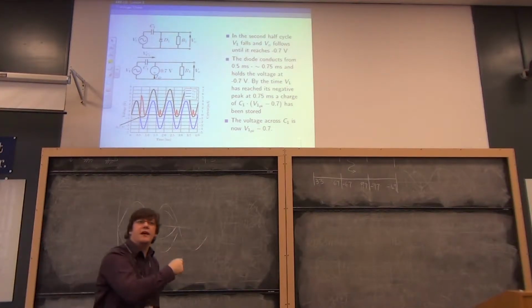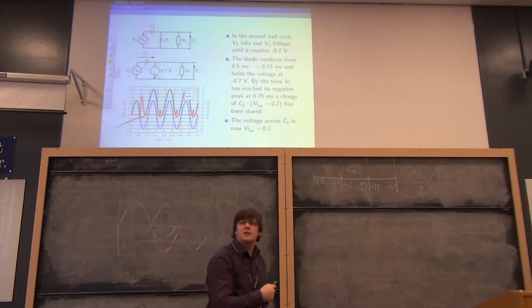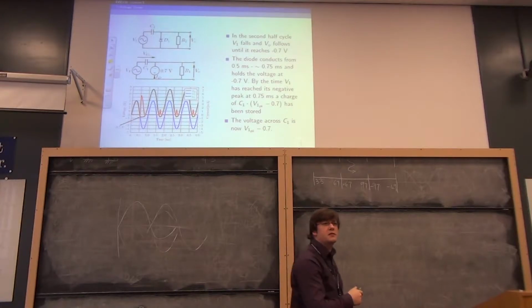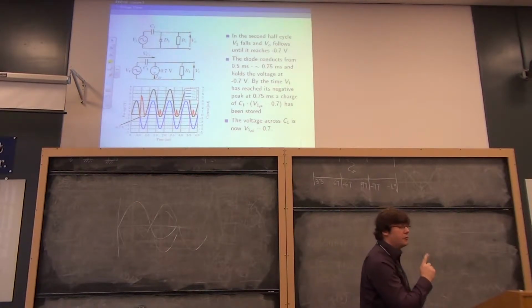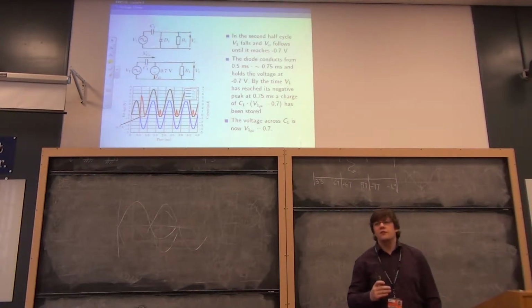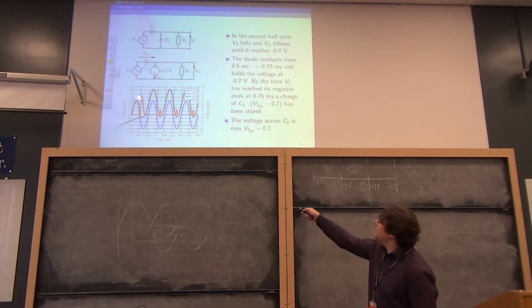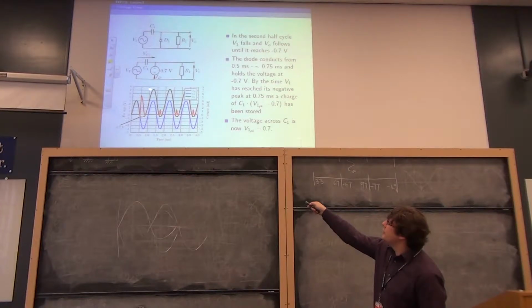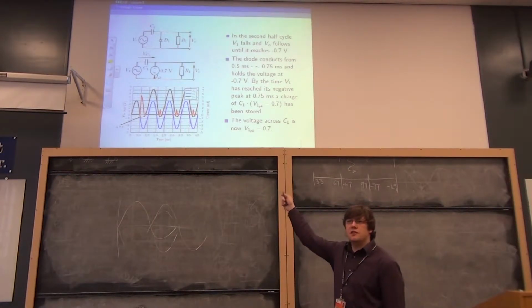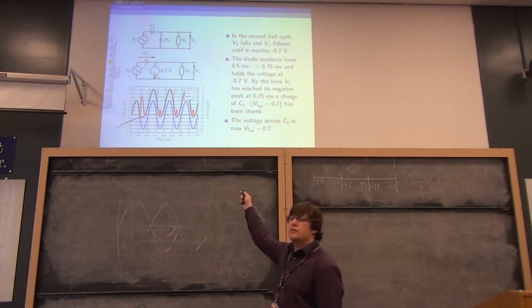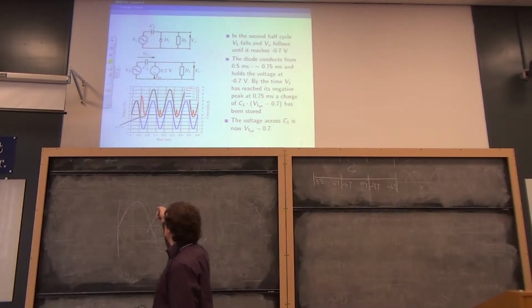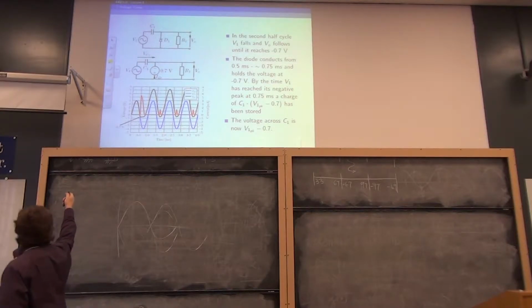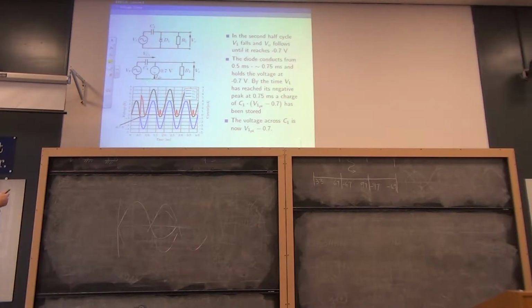So we've added an offset, a DC offset, which is the value of the voltage on the capacitor, to the input waveform. And that's why it gets shifted up a bit. So you see, this is the top peak for the first half cycle, this is the top peak for the second half cycle, and because this is steady state, all of the cycles that follow. And for the conducting diode situation, we've got the lower circuit there.